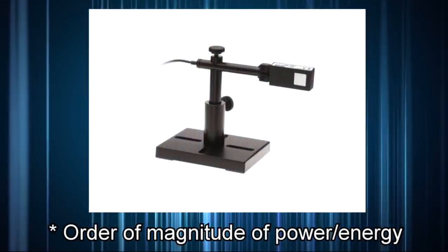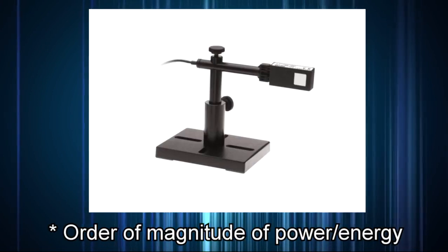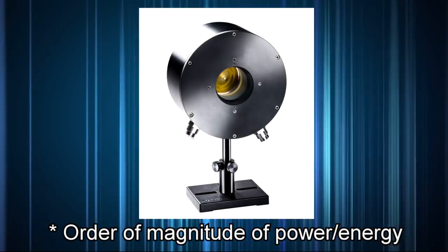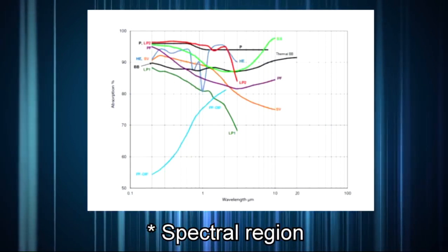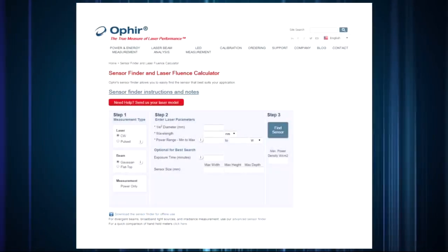The specific choice of sensor model depends on a number of parameters, including the order of magnitude of power or energy. For example, a power sensor that can measure picowatts will probably be vaporized into plasma by a multi-kilowatt beam, while a sensor able to measure multi-kilowatt beams will not likely respond at all to a few picowatts. Spectral region. Different materials absorb light of different wavelengths to varying degrees. And beam diameter. No need to panic.